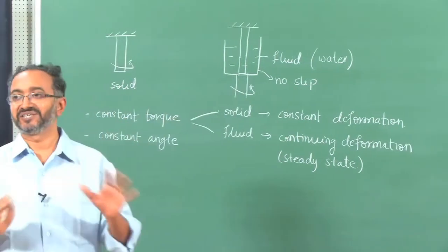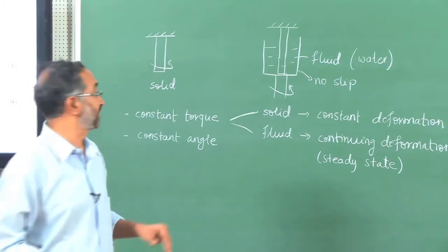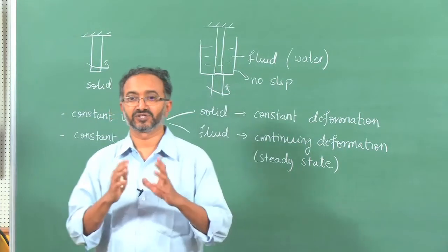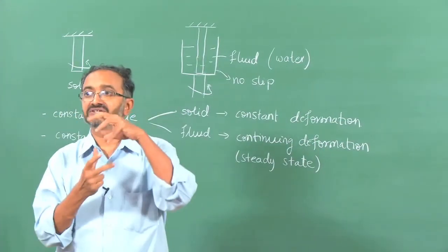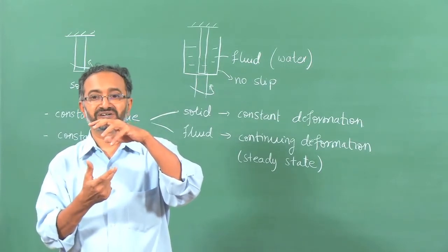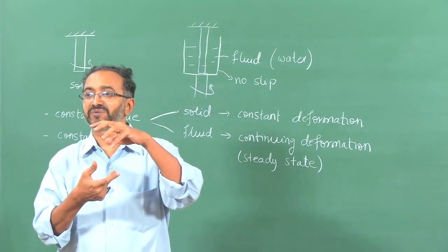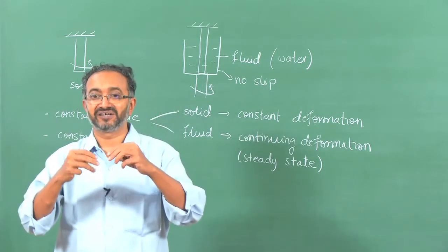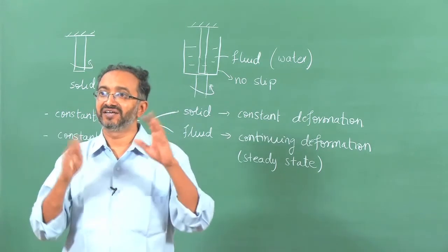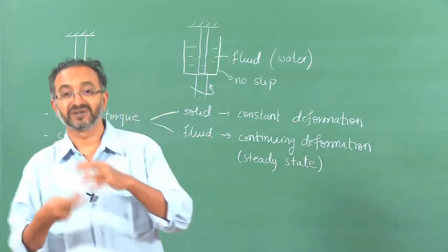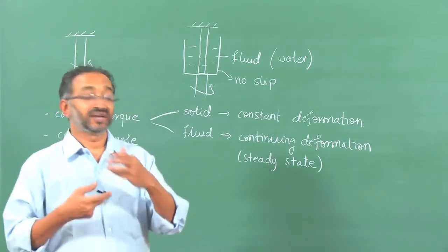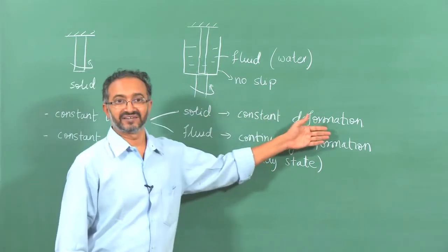Here we saw that there are two extreme cases of deformation. In one case you reach a constant deformation, and in fact it is a new equilibrium state of the solid material. If you think in terms of crystals of solid, what we have done is take the atoms away from the equilibrium position, but reached a new equilibrium, in which the strain energy we have imposed on the material got stored in the material. So, now the new atomic arrangement is such that strain energy plus its internal energy together makes the new configuration possible. And that happens in this solid-like case.